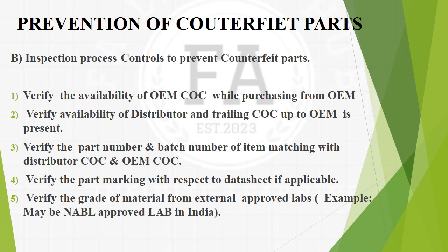Verify that the part number and batch number of the item match the distributor COC and OEM COC. So this is another way of control. If the item has one batch number, the distributor's COC has another batch number, and the OEM COC has some other batch number, then it shows that it's a counterfeit part, or the supplier has provided an item with a different batch number along with some other OEM COC.